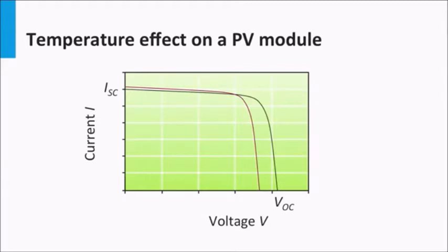On the other hand, if the temperature were to decrease with respect to the original conditions, while the irradiance were constant, the PV output would show an increase. The minor increase in current with temperature can be explained by the fact that carrier concentration and mobility increase in the semiconductor with temperature. This is consistent with our basic understanding that a semiconductor, unlike a regular conductor, exhibits better conductivity with increasing temperature and is a perfect insulator at an absolute temperature of 0 Kelvin.